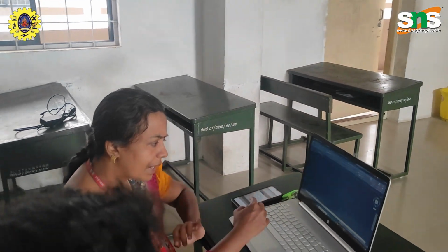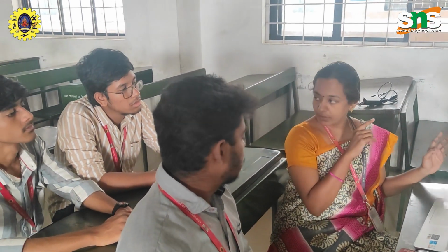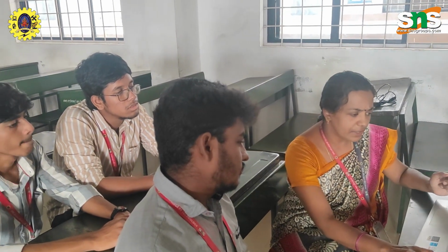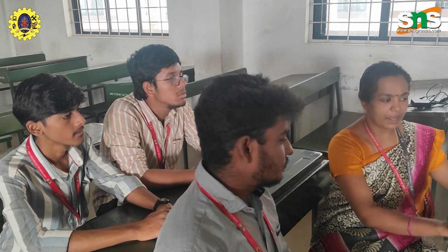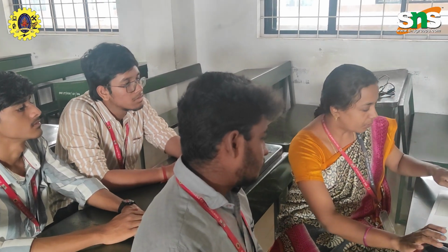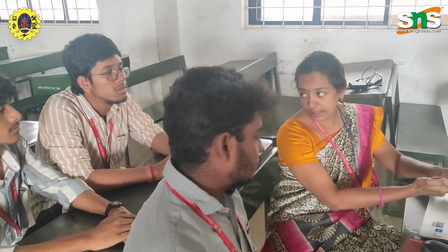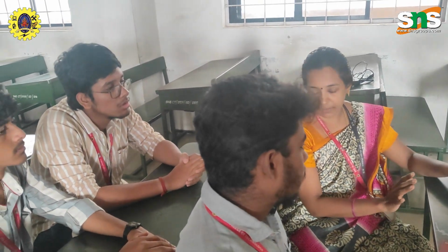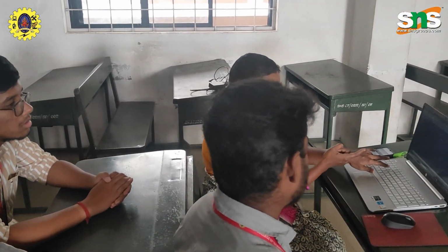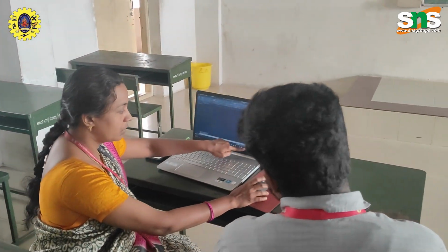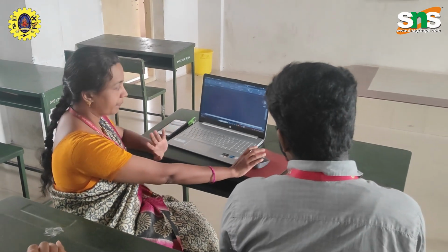Here I have selected isometric right, but for this diagram I need the isometric left option, so I have to change it. I can change it here to isometric left. This is exactly what is needed for my diagram. Instead of going with this option all the time, I can use Control E. This is the top plane. The keyboard is always more exact and prompt for a designer. So Control E gives the top isoplane, this one is the right isoplane, and this one is the left isoplane. We have to know this option, but we should not use it. That is the exact thing.